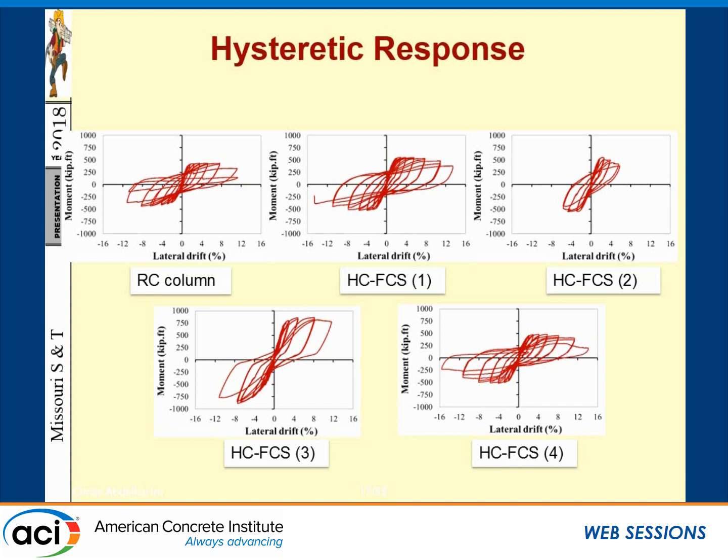Over here, this is when we use the very thin FRP. Strength-wise, this one and this one perform the same from a strength perspective because it is the same steel pipe. However, because we had a thinner pipe for the FRP, you get less confinement, you achieve less displacement, and this is the difference between this one and this one over here. On this column over here, this is where we had a shorter embedment length, and this is where you see some of the slippage.